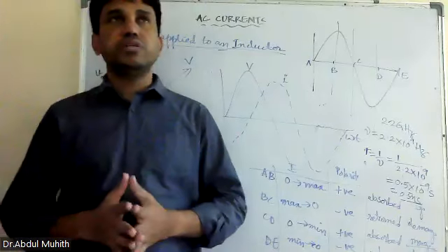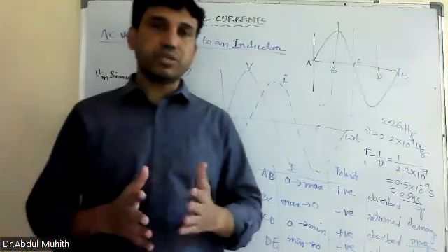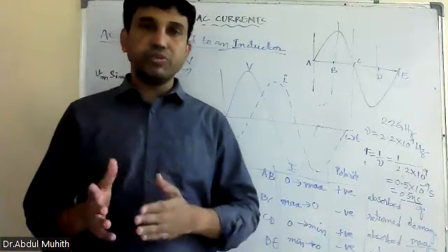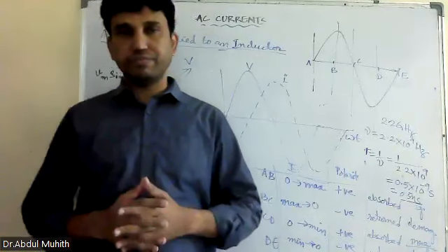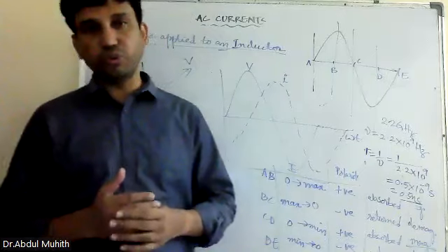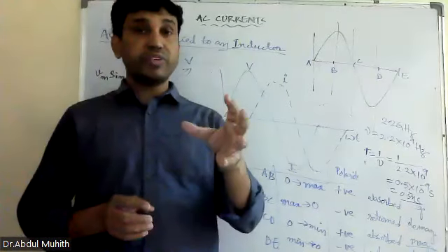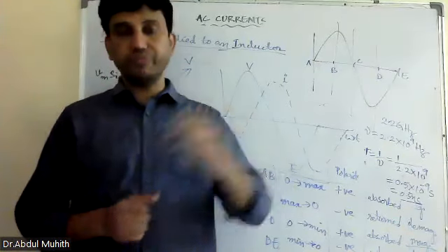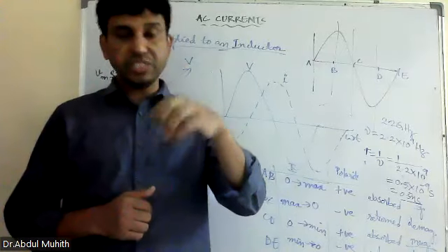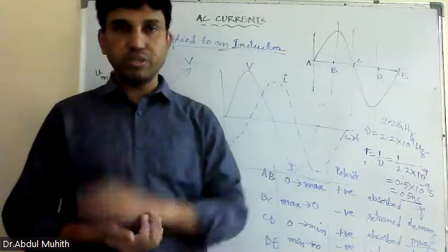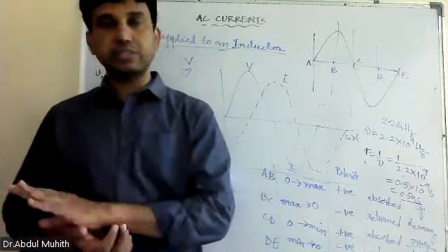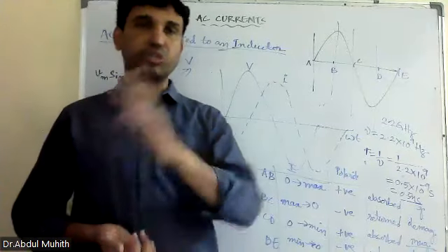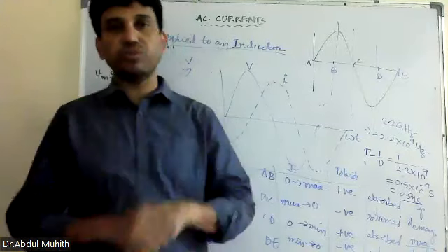Now, see here, the first law says that current coming to the junction is equal to current leaving the junction. Number one. Second one is what? Loop rule. It means the sum of potential differences in a closed circuit is 0. Means the battery minus the voltage across whatever component is there, if you add it, it will become 0.